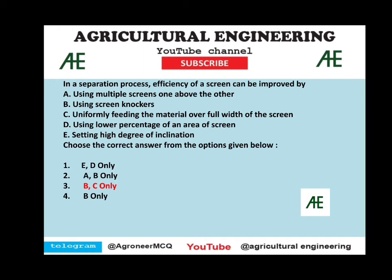So in a separation process, efficiency of a screen can be improved by using multiple screens one above the other, using screen knockers, uniformly feeding the material over full width of the screen, using lower percentage of an area of screen, setting high degree of inclination. Choose the correct answer from the options given below. So the correct answer is using screen knockers and uniformly feeding the material over full width of the screen.